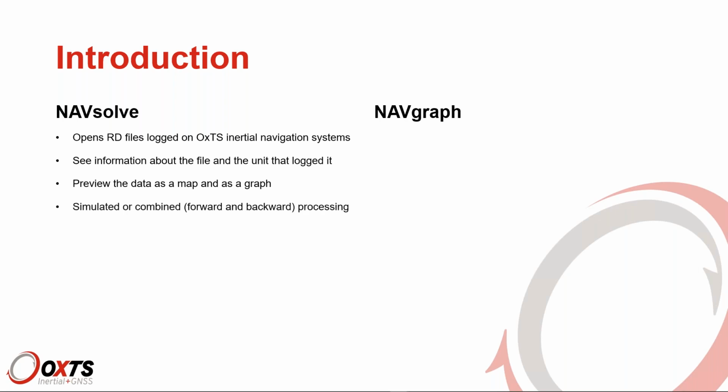You can choose what processing mode you would like, that's simulated or combined. We will have more on that in a minute. You can add RINEX files, so differential corrections files, to improve the accuracy of your data. You can modify the configuration, so whatever configuration you had in real time that you've logged your data with, you can modify that either because you realize that the configuration was wrong in some aspects, or because you want to check the effect of modifying a few settings.